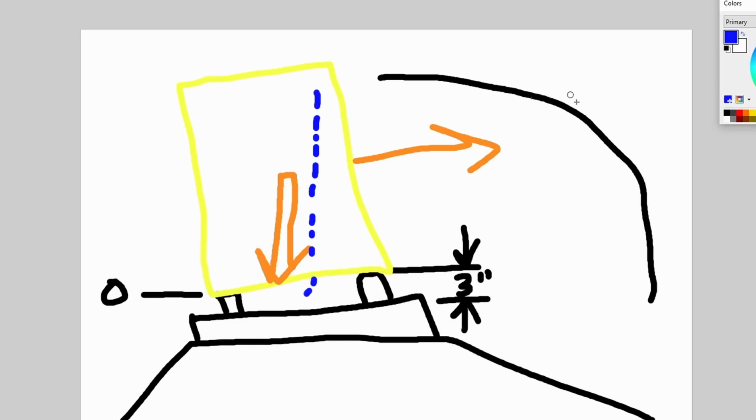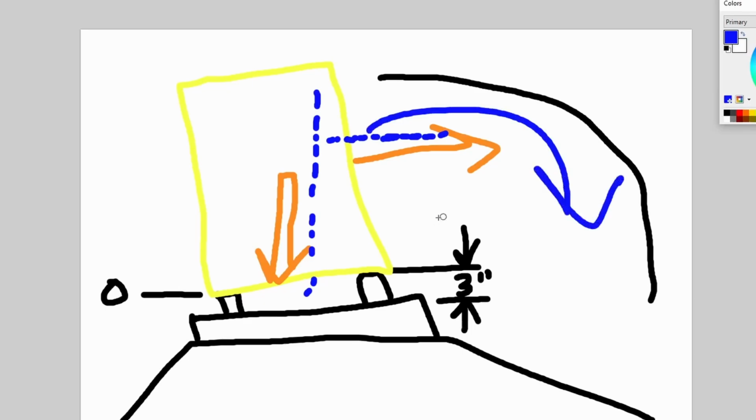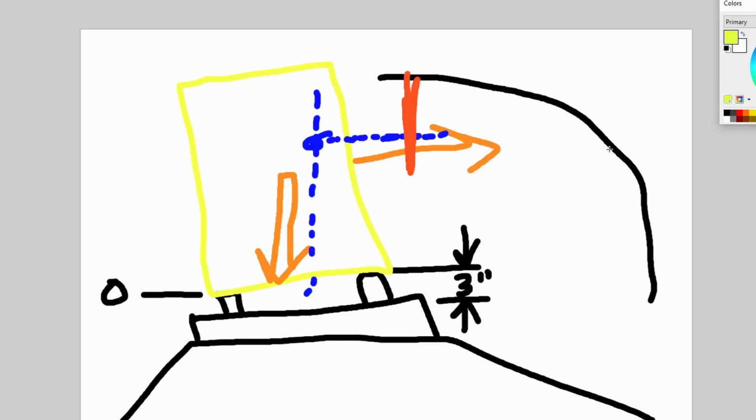But as we turn hard left, it wants to be thrown to the right, and we can counteract it a little bit with superelevation, but we can't let it go too far to the right as we turn left, right? At some point, the train will tip over, because we'll get too far past our normal center here. And so we cap it and say, well, you can't have any more than this. As you add superelevation, perhaps normally, if you're going 79 miles an hour around this sharp curve, you'd be here. But because we added the elevation, well, guess what? You're actually only here. So you can run that speed.